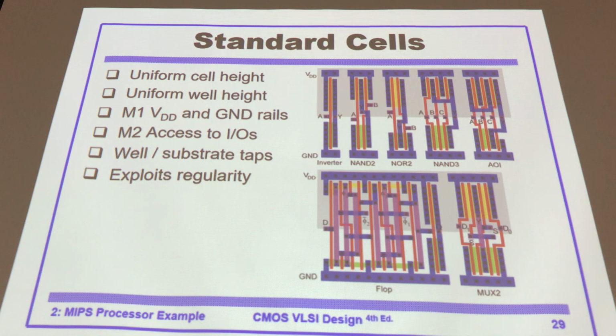Their height should be the same, such that you can simply connect them, right? Simply abut them, 就并在一起，接在一起，立刻就用 power rail can go through in a straight line. Okay, and also the output can connect to the input, something like that. So it's easier for your layout if they are the same height. 通常是高度一样的，这样比较好并接在一起。And without violating design rules.